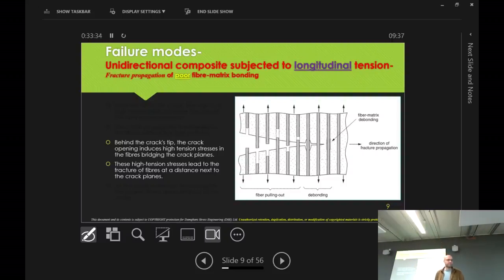No, not that one. Debonding. Where is that happening? I feel like it's happened all the way along, and then specifically that one. So you haven't applied enough pressure. Yeah. Let's say your autoclave was messed up, or generally it doesn't happen with autoclave. Autoclave is pretty damn good. Hot pressing too, if it's flat plates, hot pressing is good.